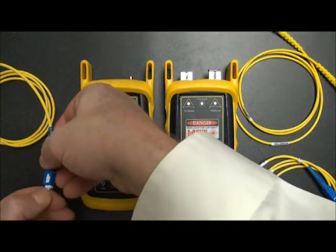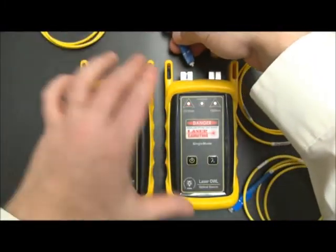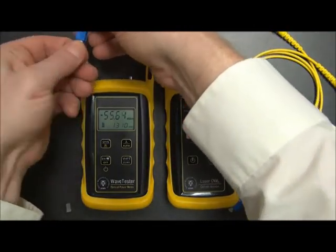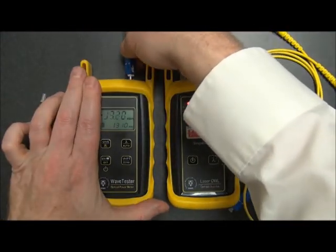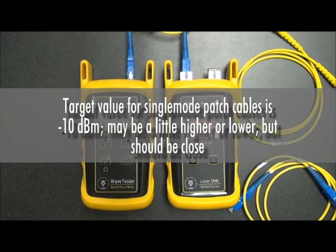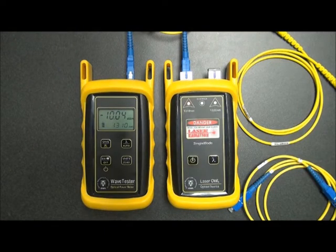First cable we want to check is the cable we'll be using for the power meter side of the test. So we plug it into both ports. And our target value is minus 10.0. Now as you can see, we have a value of minus 10.0 here. This is pretty close to minus 10. Now the actual value is going to be higher or lower, but it should be fairly close to minus 10.